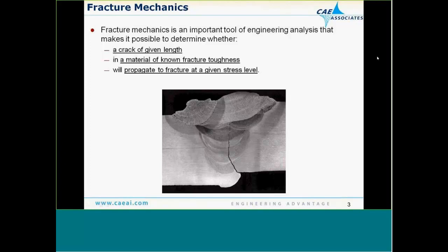Knowing the size of the flaws and the current cracking, and knowing what the loading is, we could use fracture mechanics analyses to determine, based on the given flaws that we could see in the existing ones, how long until those cracks would propagate. And then, using safety factors and so on, you can set inspection intervals. You can say, okay, you can turn these other ones back on, you can run for another 10 months, and then we recommend you inspect again, and then you redo the analyses and so on. That's the idea of how fracture mechanics would get used.